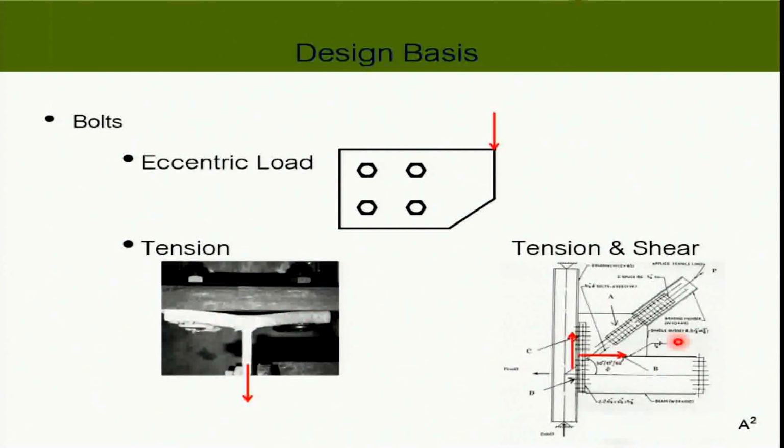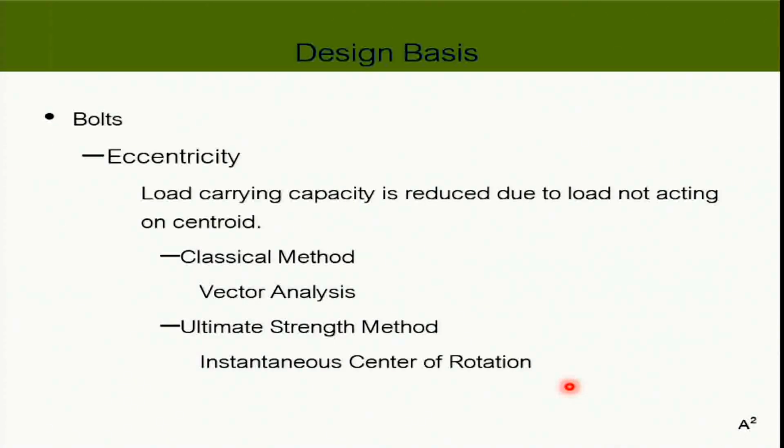Okay? And we can have a case like this where your bolts may carry tension and shear at the same time, and therefore we need to combine the stress. Use the equation that we previously saw. Okay? Now, if you have the eccentricity problem, we need to mention the eccentricity a little bit because we're going to need to consider this when we design the shear connection for the beams.